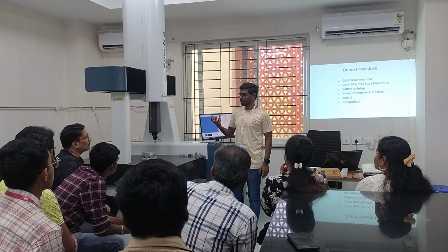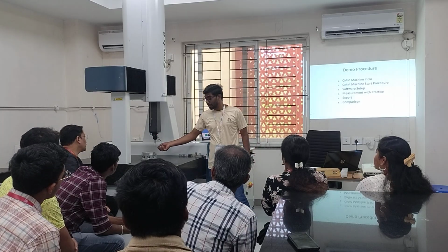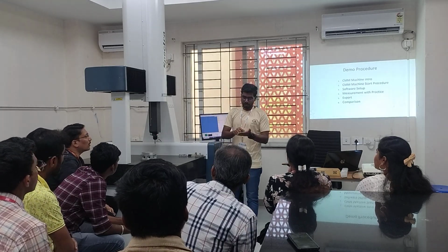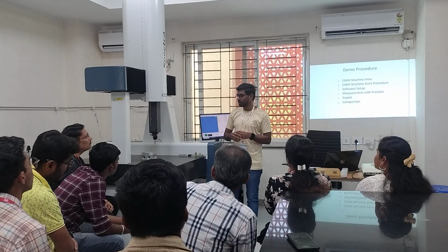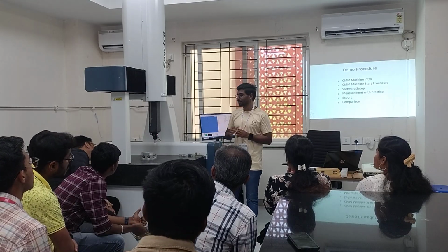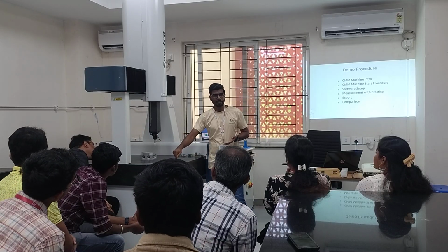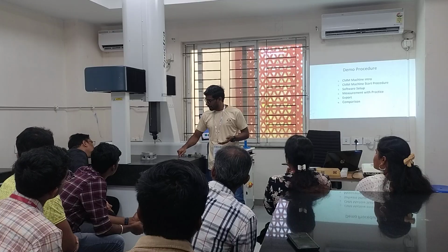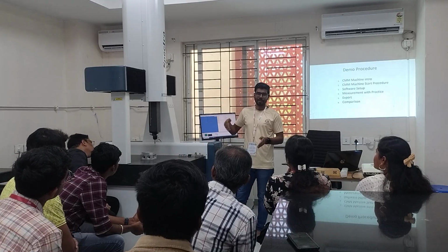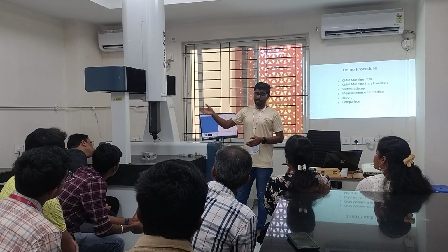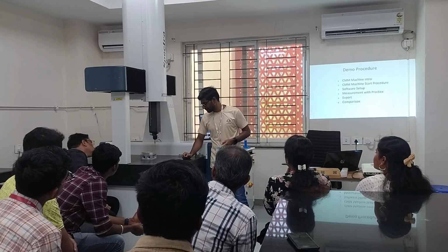It can be sometimes, but yes, it is very scratch resistant. It is a very hard material, similar to diamond, we can say. Not equal to diamond, but similar. That is why we do not use diamond here. It is scratch resistant because several times this probe is going to touch our part. If it touches several times, even water droplets can carve a way into stone, so the probe itself could get scratched. That's why we use ruby, so that it is not getting scratched.